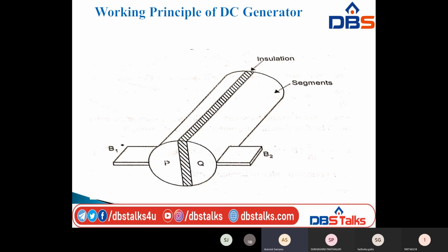If we observe this diagram, there are P and Q, the two equal segments. Here I am separating the ring into two equal segments, P and Q. The segments are insulated from each other and also from the shaft. Here we have two brushes, B1 and B2. These two brushes touch the segments P and Q.